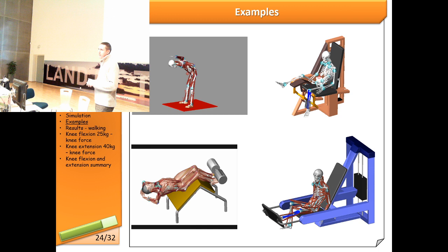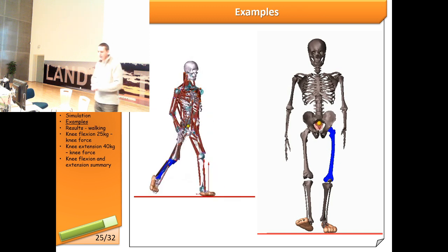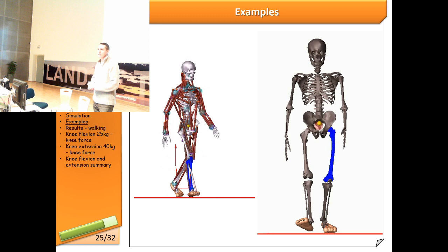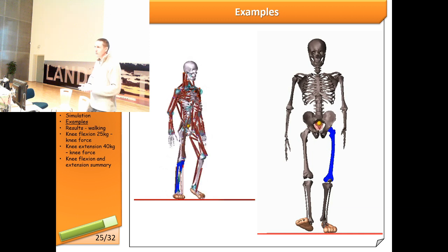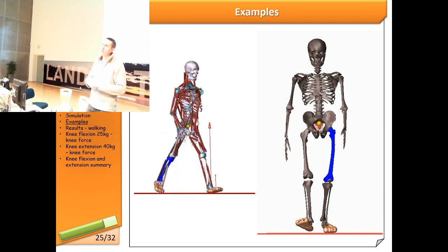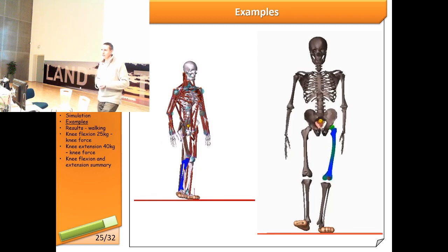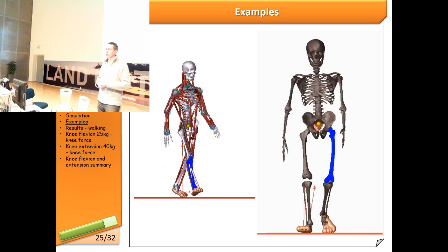Okay, this is walking, and this is walking from the side. You can see that he has this kind of bear-like feet, and those elements are for contact detection. They have to be a simplification because in our simulation the foot was rigid. Normally when you have a toe off, you're actually bending your toes and changing the foot geometry. Here it is simulated by the balls under the toes, which are slightly moved back so that he could actually make the toe off without dragging his feet through the floor. And that's based on recorded motion.